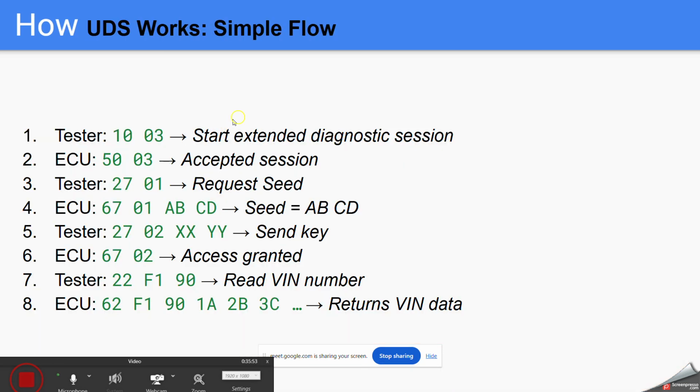And one more point to remember is that whatever communication happens between the ECU and the tester, it will always be done with the help of a transport protocol, because whatever data we are sending, it will always be more than 8 bytes. And generally, we have to give the buffer size of the diagnostics, so we always give either 1024 bytes or maybe 4096 bytes, based on how much payload or how much data you want to send to or receive from the ECU. So that's why it is always more than 8 bytes. If it is CAN, it is always more than 8 bytes only.